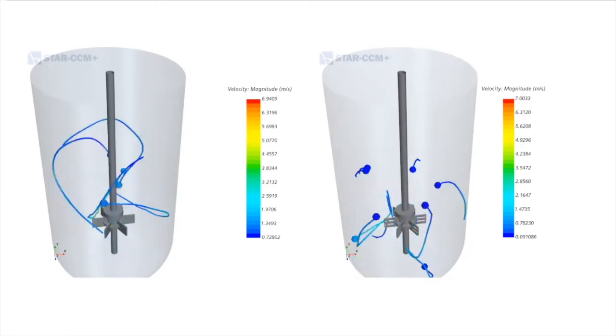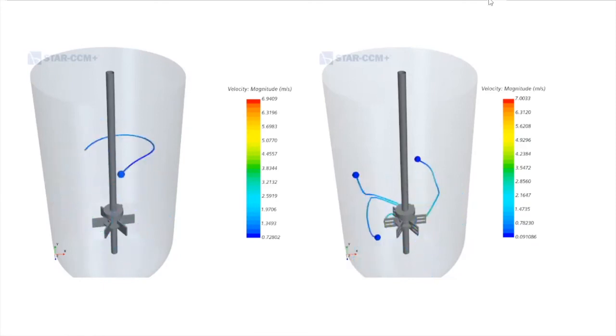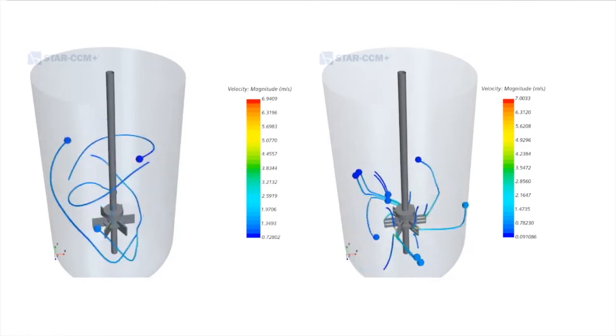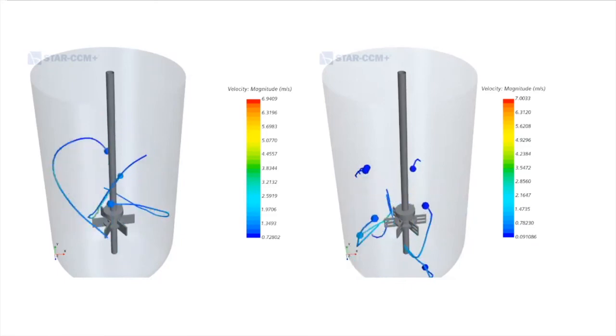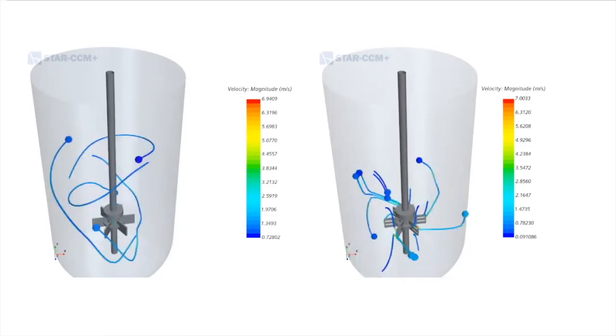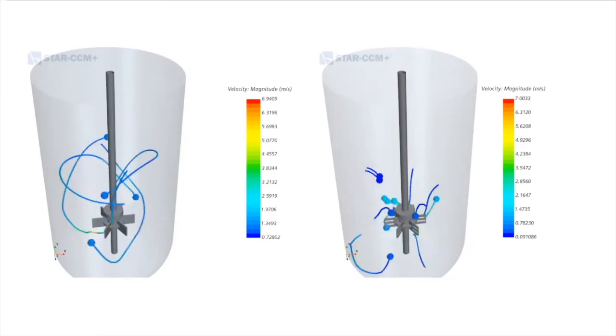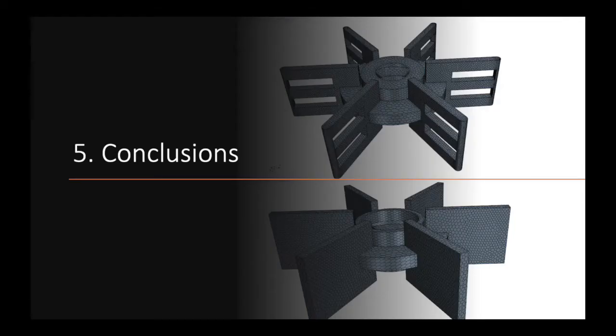As for the Rushton turbine, the flat surface produces an outward displacement, boosting the fluid towards lower mixing regions on the top. On the other hand, the perforated blades do not produce the same boost due to the reduction of the surface area. As a first conclusion, it can be seen that the results match the literature survey. The power number for the new design was on average 45% lower in the turbulent regime.